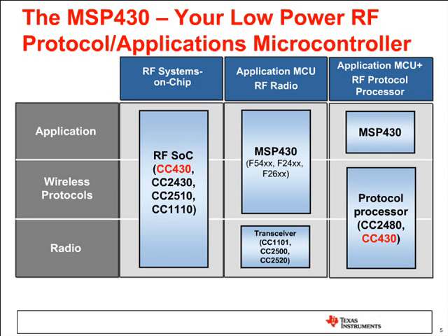You've got the radio transceiver, that's just the physical communication between devices. You have the software layer, which is going to be specific to the wireless protocol. And you can split up the software into two pieces, right? The wireless protocol, which means you have a 6LoWPAN, a wireless SMBus, and then you have the application, which is whatever it is you're doing, heat cost allocator, or sub-metering application, etc.